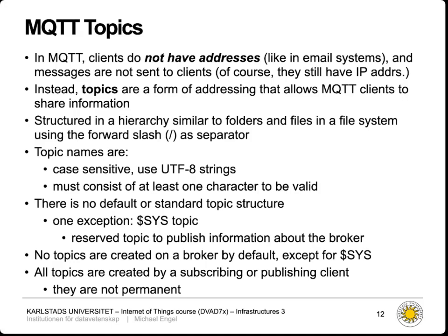But instead of specifically addressing a single client, because in IoT systems, clients can change, they can run out of battery. We want to maybe add clients on demand when the system is growing without having to reconfigure all the system and reboot and reconfigure the broker. So the idea is really to indicate a set of topics.